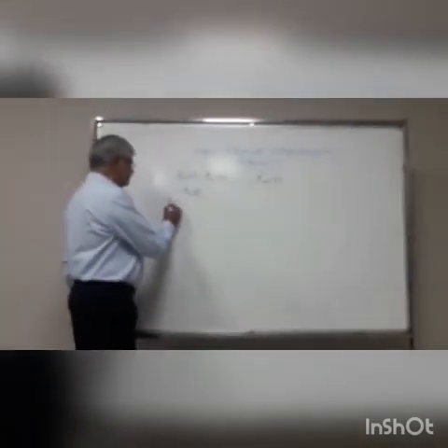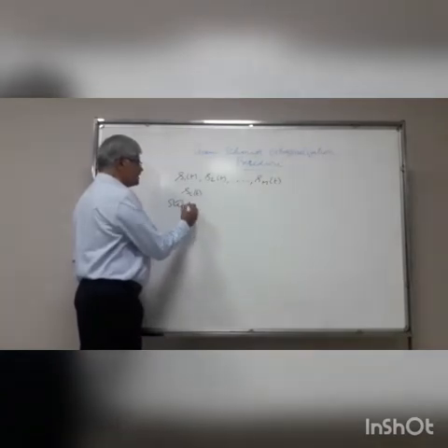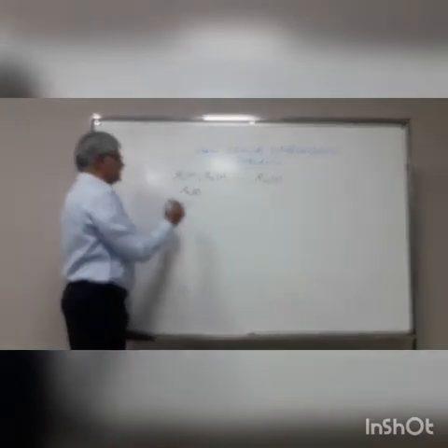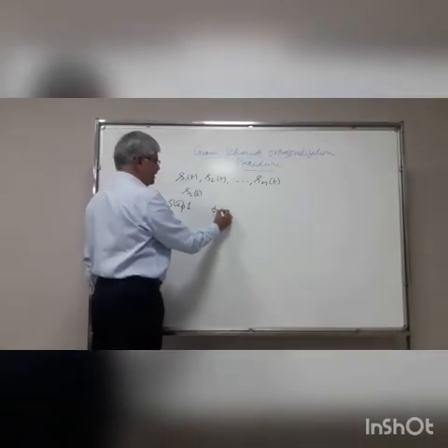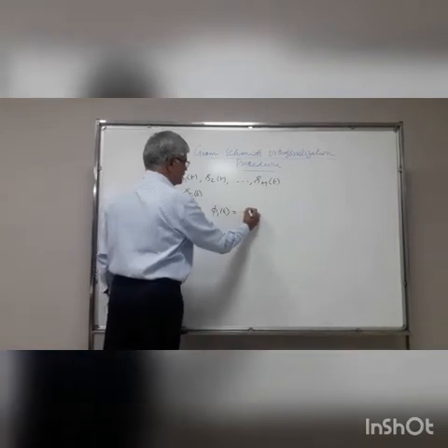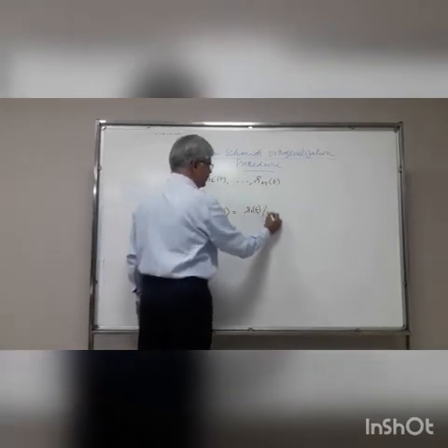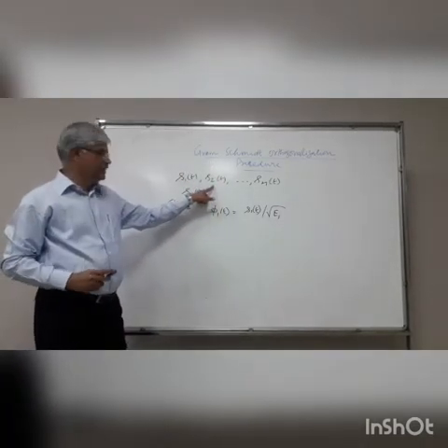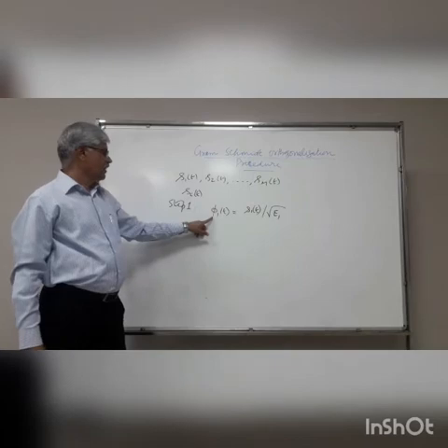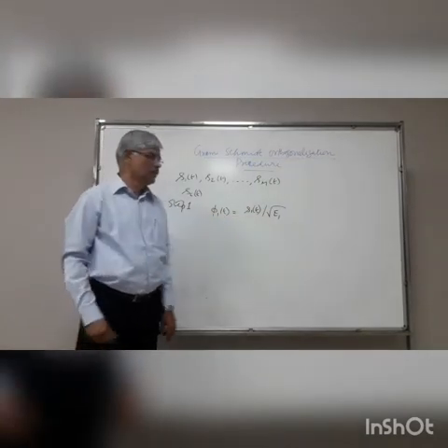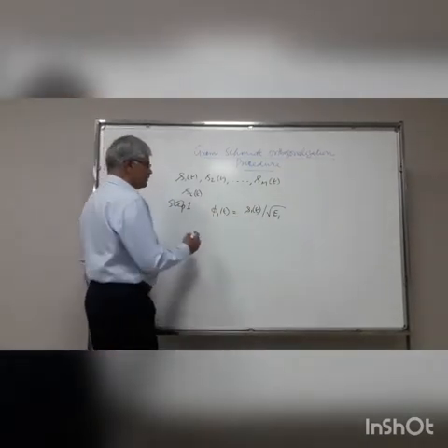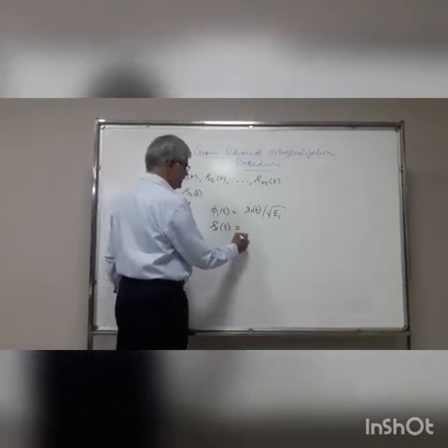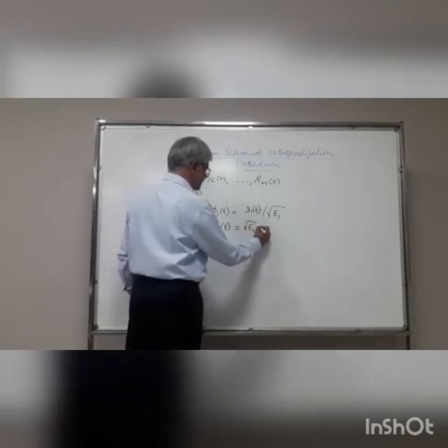Step 1. First we have this with us. We will start with representing phi 1 of t as S1 of t divided by root of E1. These are all energy signals which have finite energy. So phi 1 of t equals S1 of t over root E1. That means S1 of t can be represented like this: root E1 times phi 1 of t.